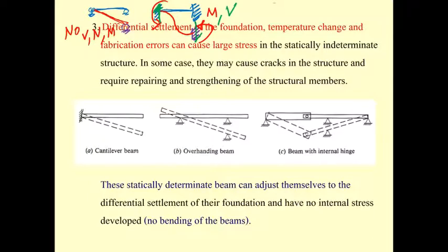This also, if it occurs, is going to produce cracks on your structure. This also occurred in some buildings at SUT, because when we built our university, we came during the summer. When we came during the summer, the soil in this site was really stiff. So when you investigate that soil, the soil is going to have large strength, and then you design the building based on that.